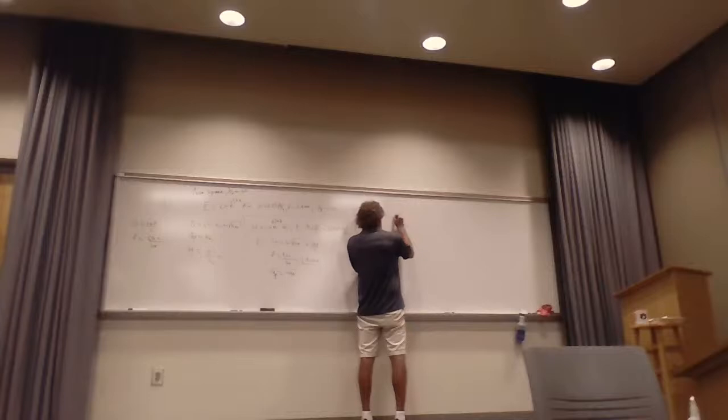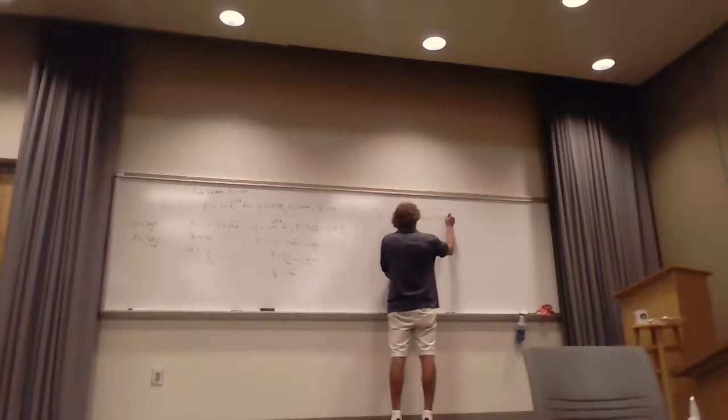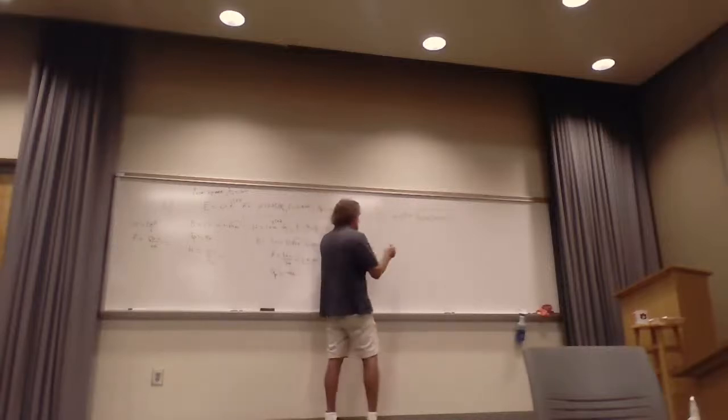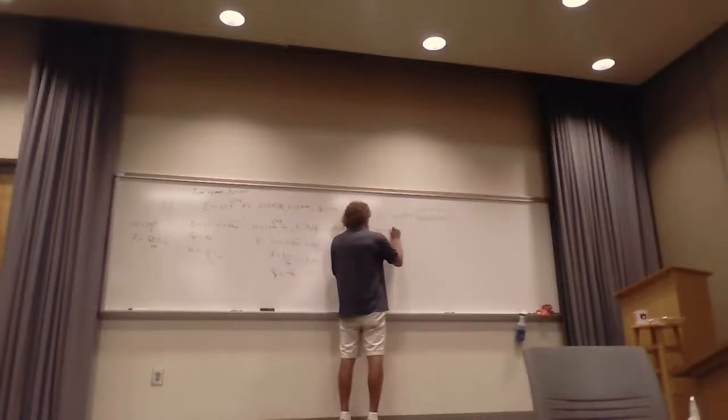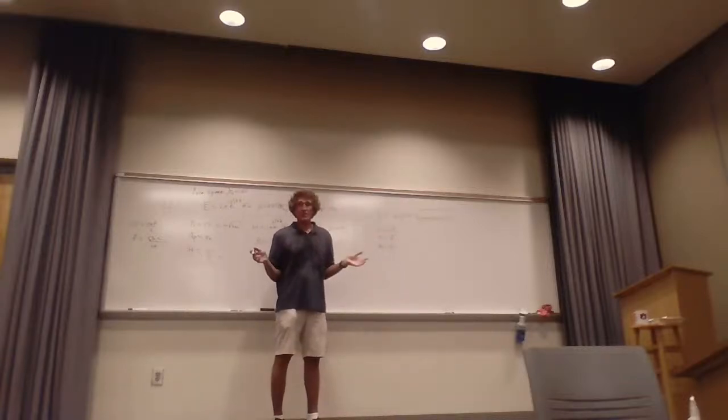Anyway, this is equal to alpha plus j beta, and this is straight up, just stick it in and turn the crank, and make sure you know what you're doing. So it's the square root of j omega mu over sigma plus j omega epsilon, right? That's it. Omega is equal to 2 pi f. Sigma on this one was 5? Yes, 5. And epsilon relative was 72, is that right? Yes, sir. All right, the only thing you had to do was turn the crank on this. There's no tricks at all.